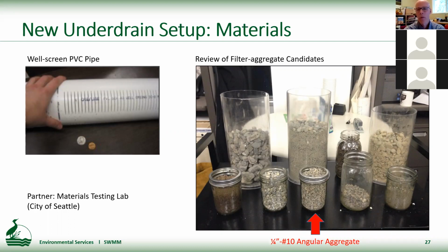And of course, the washed and angular are very important characteristics of the material. Particularly that it has to be this fractured angular material that allows for the mounding of that material and a very reduced incidence of sloughing or raveling. Next.